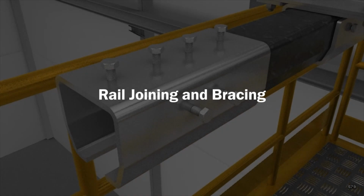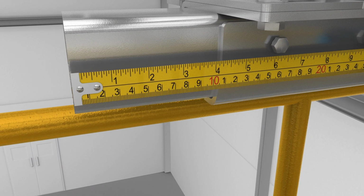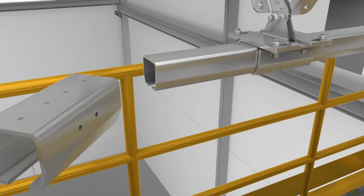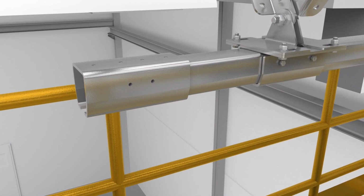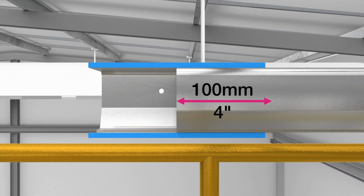Rail joining and bracing. Where two sections of rigid rail are to be joined with a rail splice directly adjacent to a clamshell assembly, ensure that a minimum of 4 inches of rigid rail protrudes beyond the clamshell assembly. Add a rail splice to the existing section of rigid rail that is being held captive by the fixed clamshell assemblies. Ensure that the rail splice is positioned onto the rigid rail to achieve a 4-inch overlap. This will ensure the adjoining section of rigid rail will similarly have a 4-inch overlap.